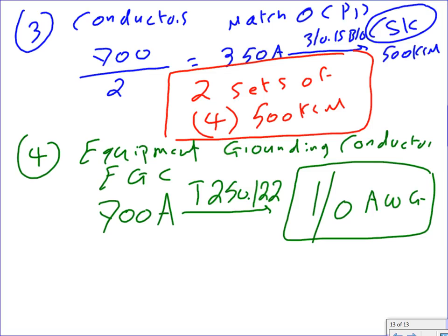Now, Brad, if you have an EMT conduit or rigid or intermediate, do you need this conductor? No. We don't need it. If it was an EMT conduit or rigid or intermediate, you don't need it. Hospital, they need it. Yes, we need redundancy in the ground. Yep. Hospitals, you need it in the ground. Commercial building, no. Absolutely.